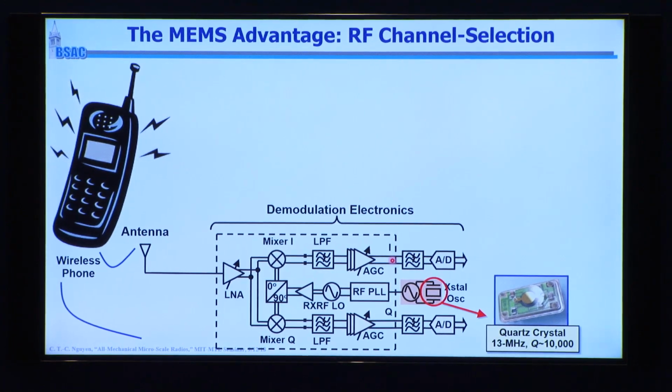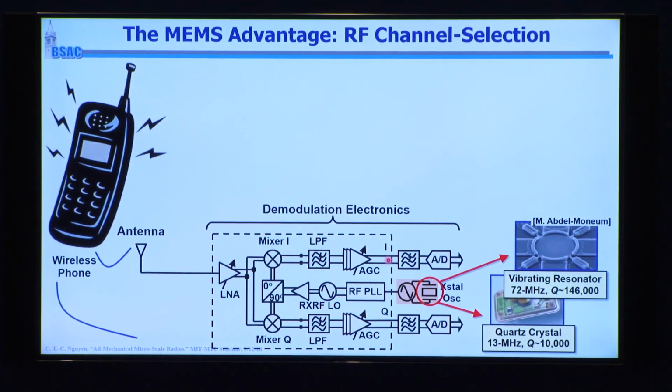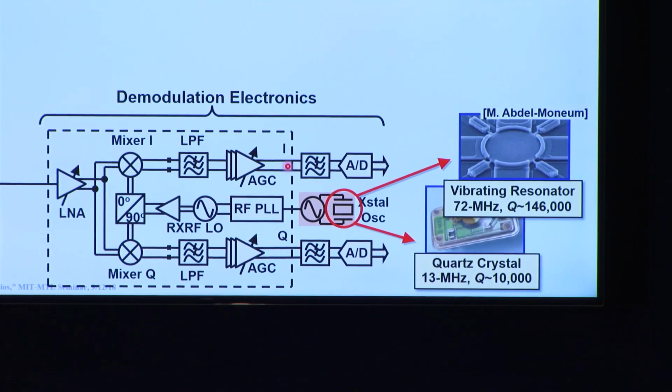You have something on this that serves as a reference, so a timing reference, and that's usually a quartz crystal oscillator. And so this delves into the practical side of MEMS. A lot of what I've done in my early career has been attempting to replace quartz crystal oscillators. And so now what we're seeing is MEMS doing that.